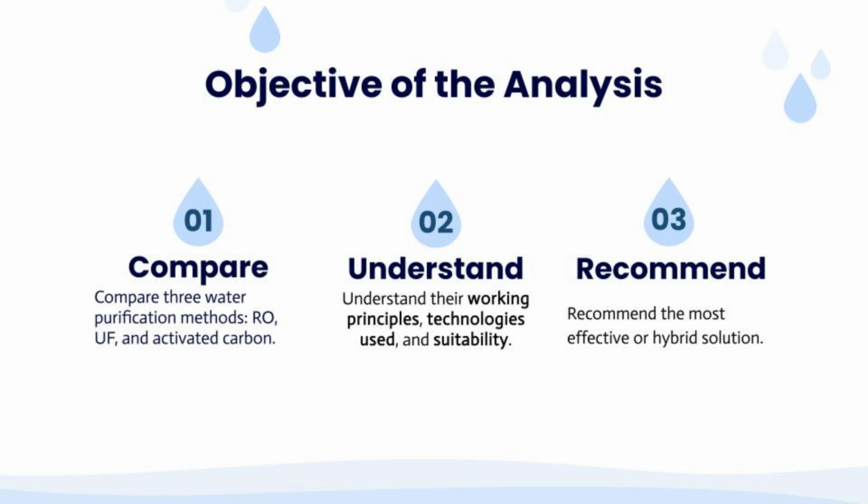The main objective of this analysis is threefold. To compare 3 important purification methods: reverse osmosis, ultrafiltration, and activated carbon filtration. To understand their working principles, technologies involved, and suitability for different users. And finally, to recommend the most effective or hybrid solution based on sustainability, usability, and feasibility.